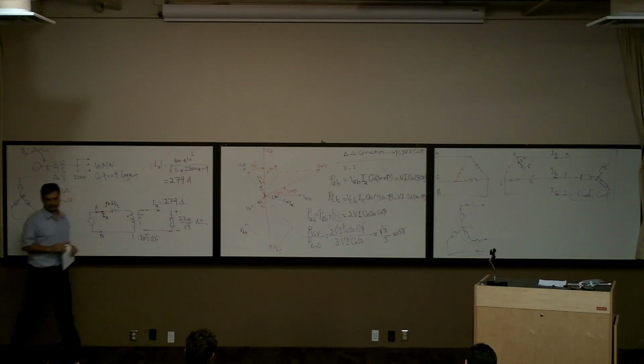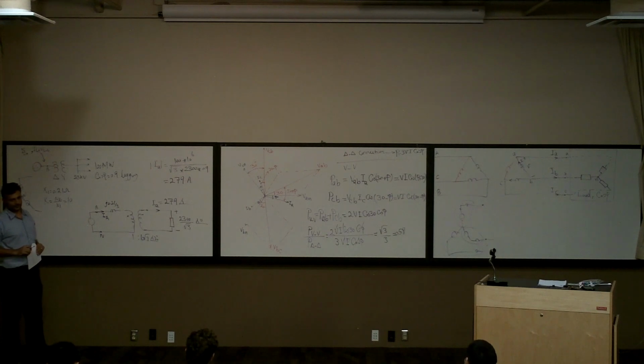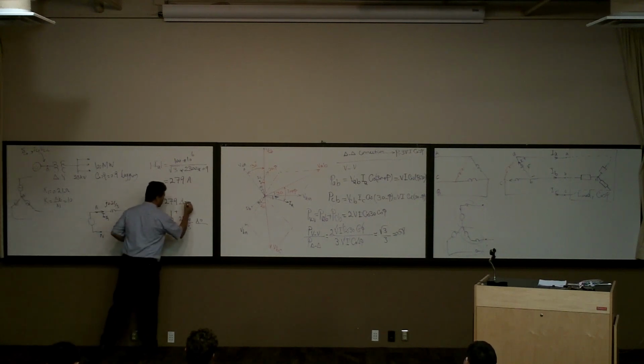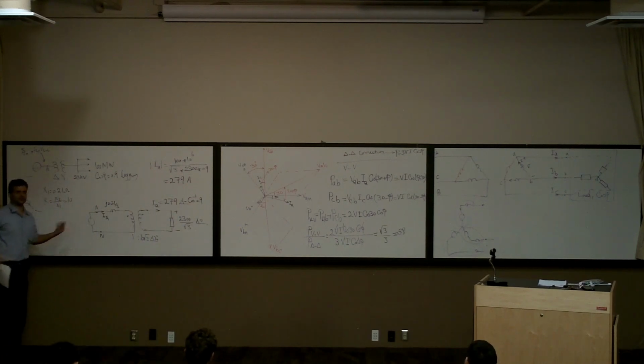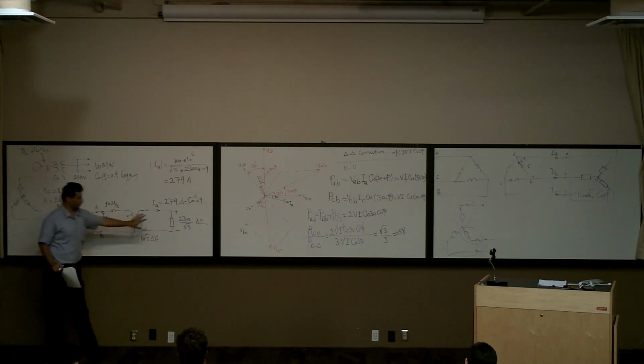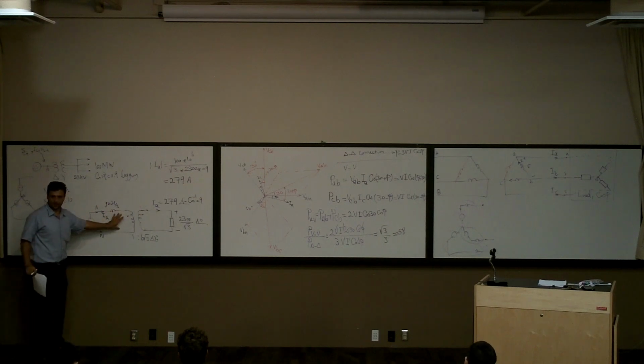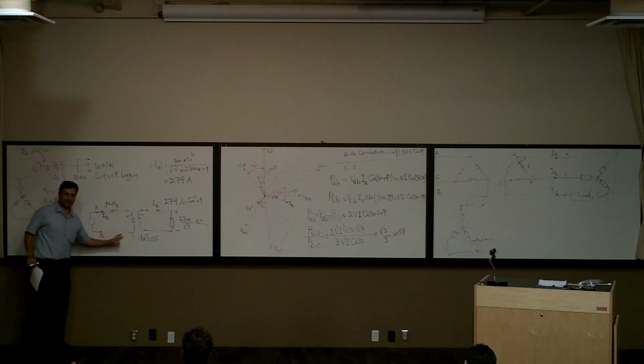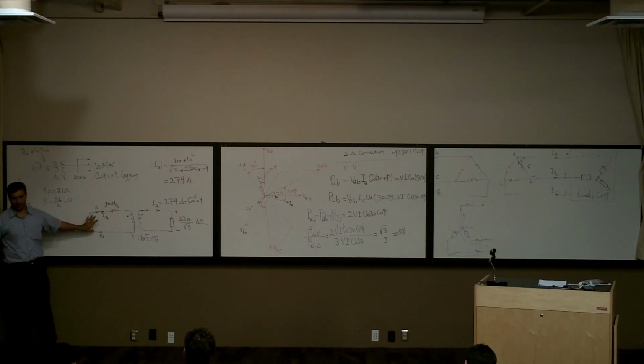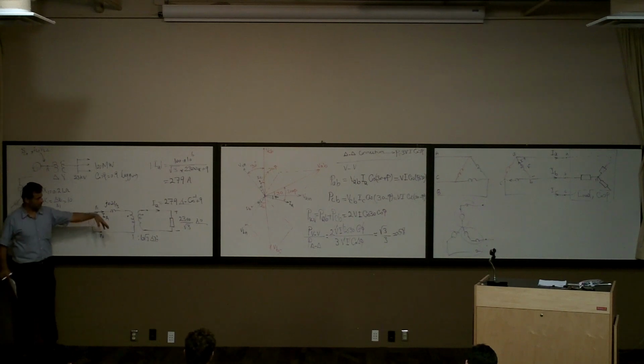So how much is IA here, with how much angle? It's minus cosine inverse 0.9, right? I'm going to stop it here because the rest is very, very simple. It says how much is the VL to element, right? You know this voltage. Just bring it here. You write the KVL here. The rest is in the book, you can read it. You calculate this voltage, right? Let's say we calculate, I don't know, 1400 volt with some angle.